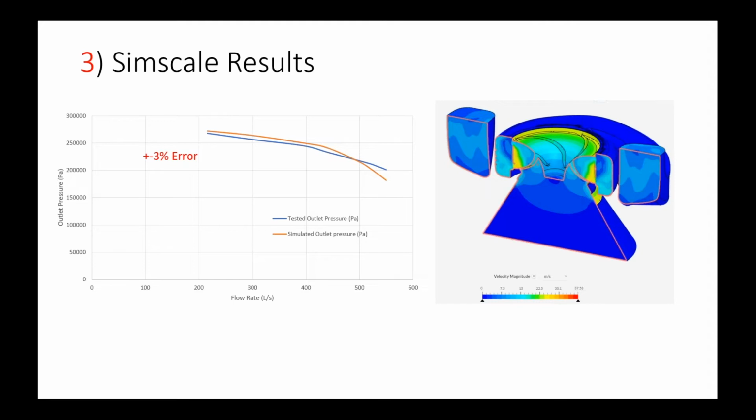This case in specific took about 23 minutes to run. It's a much larger pump, so much more cells, larger domain, and to be completely honest, the geometry, as you can see to the right, is not entirely cleaned for CFD. So basically what I did was I took the assembly, which is really loaded with lots of detail, closed the gaps, loaded it into SimScale, extracted the fluid volume, and it takes about 4 clicks. Then I have the fluid volume, which hasn't been cleaned, it's quite nasty. I just threw it into the solver and ran it. And despite that, it still only took 23 minutes to run.